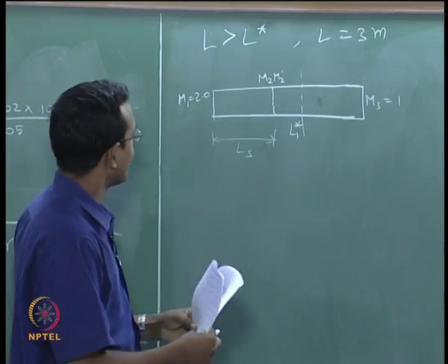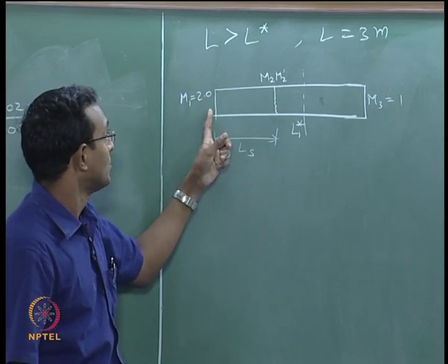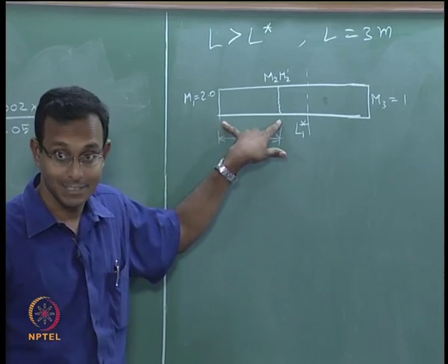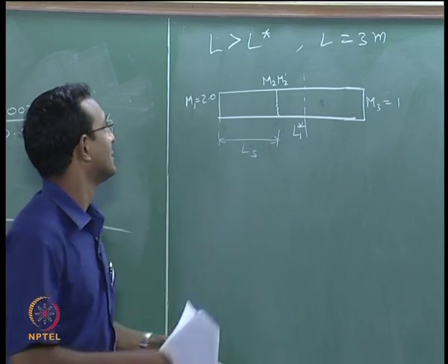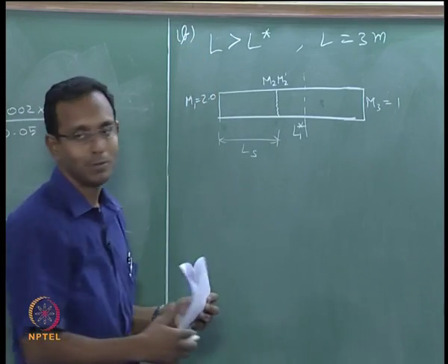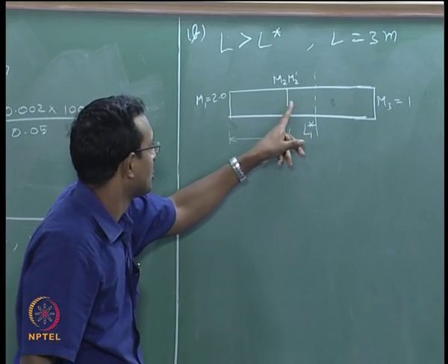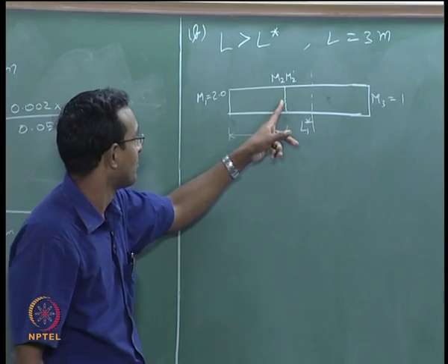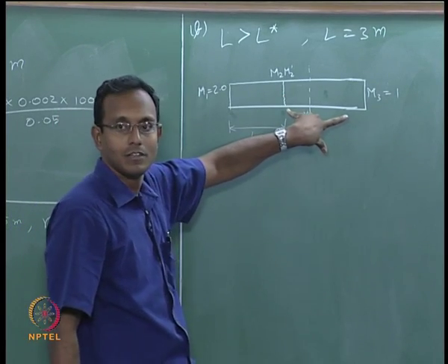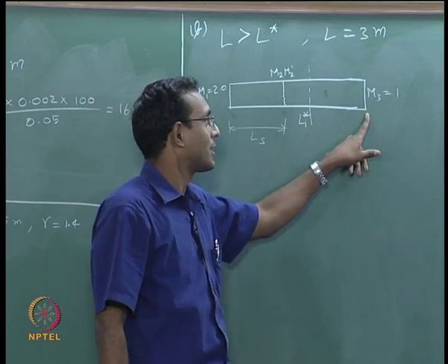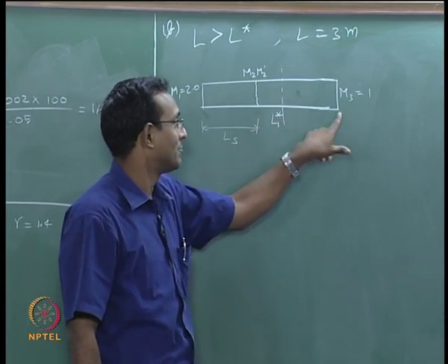So, how will I solve this? I am going to first treat this part of the problem as supersonic flow going some length less than L star, which is just now we did the problem 2A, that was this problem, and this is 2B. I keep forgetting to label these problems, this is 2B, and so I will solve this as if it is 2A. After that, I have a normal shock problem. I will just go to normal shock tables and jump from here to here across this. Once I do this from here to here, remaining portion, now I have to see if I get this Mach number to be 1 at the exit. So, I will again solve this as my 2A problem, and I will see if this matches.